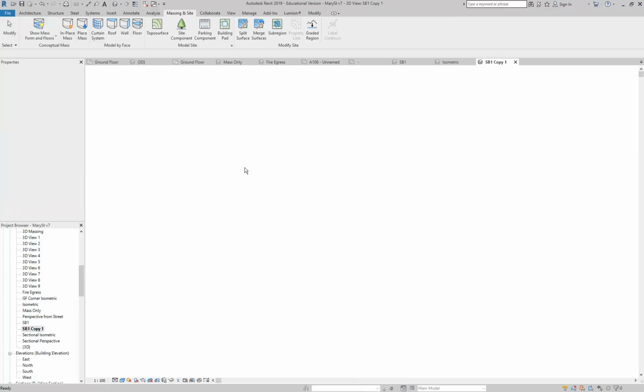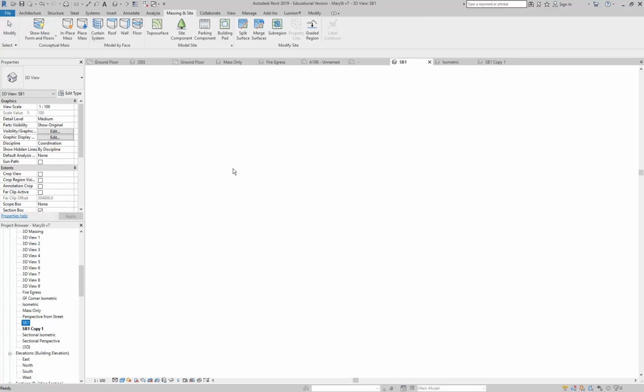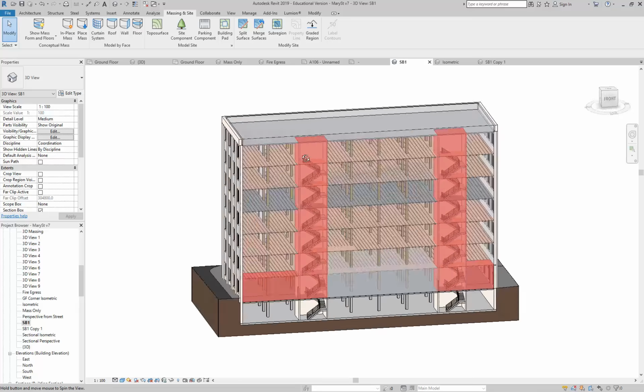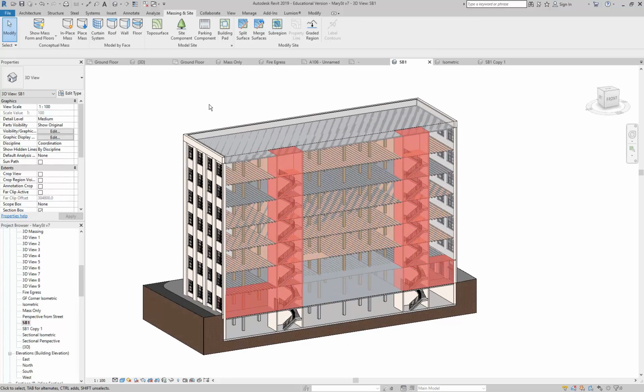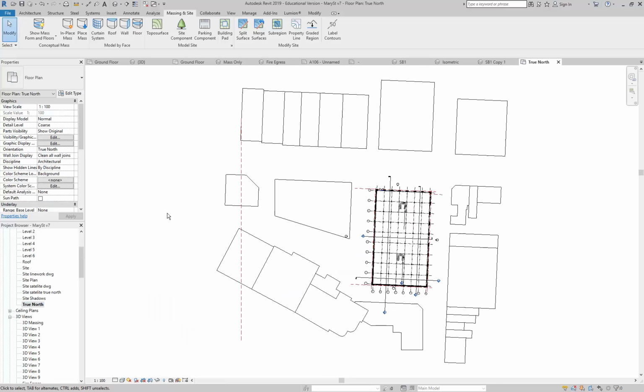So hopefully I'll give you some ideas for a presentation and keep Dinah and Janet happy. And I know they've got some good ideas for progressing things beyond this, but daylight, and then also you can try doing some rendering as well. So now what I should have mentioned, which we don't have time for today, but sorry. If you want to do some rendering, just draft level rendering to show sunlight entering your spaces, you need to make sure that you've set true north, and that's something that I thought I had done in all of those files that I gave you, but you might need to check it. Yeah, I know we've gone through it with you.